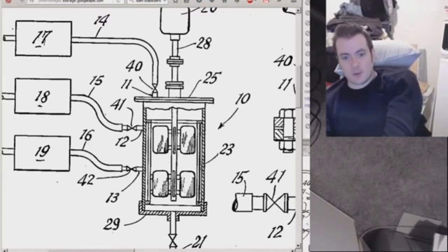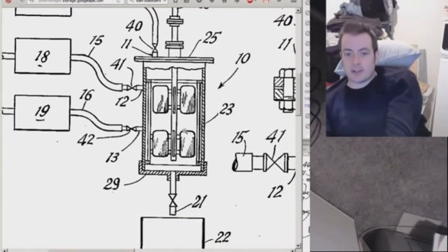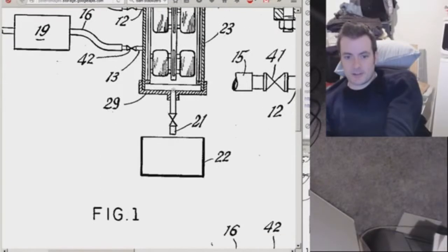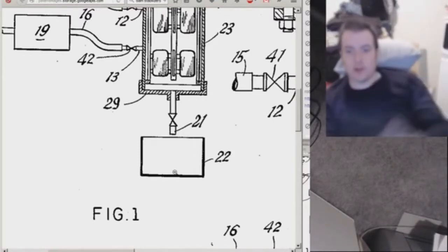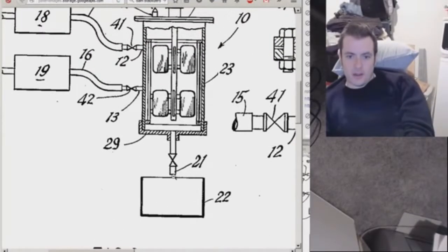And these two substances will mix by these fins going really fast, mixing it all together inside the molten plastic, and they'll start to react and create a lot of pressure, and that pressure is going to force it through this tube into a mold that will create the shape of your foam when it comes out. And the CO2 gas is going to want to expand while it's in the foam, which will create little air bubble pockets in the foam, thereby creating the cellular structure of foam.